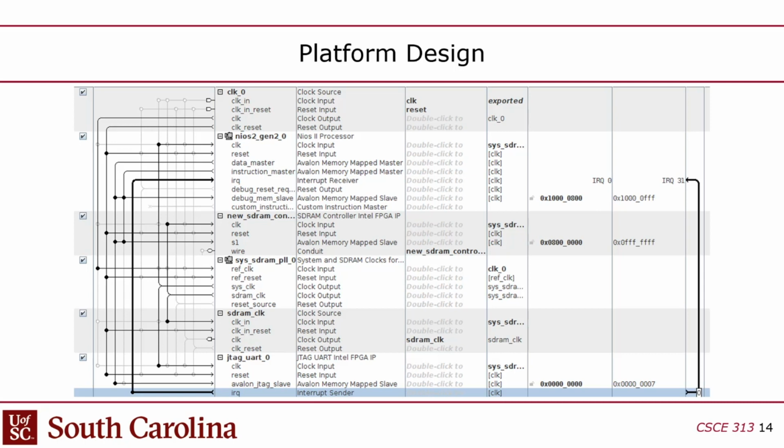Yeah. Except the reason that's not practical is that some of these are wires. Clock is a wire, reset's a wire, but this data master is not. This data master is an Avalon master, and this is actually comprised of multiple signals. Now, luckily, Avalon's actually not that complex. It's pretty simple. We'll actually be building an Avalon peripheral in this class.